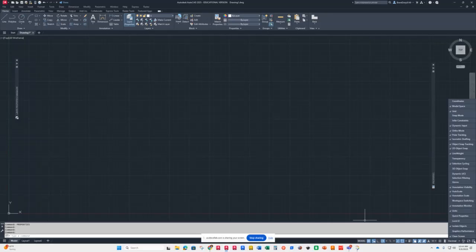So then you have to go in and set up your grid to the size you need it to be, right? So if you needed it to be 0.25, or 3 millimeters or whatever, you'd have to go under the grid settings and fix that. And you're like, what do you mean? Well, right now I have it visible. And of course I have model space visible because we're going to use that. Snap, I don't have it turned on. You know why? Because I don't use it.